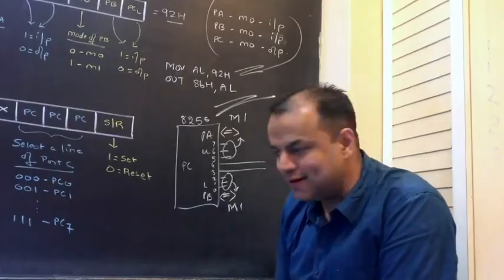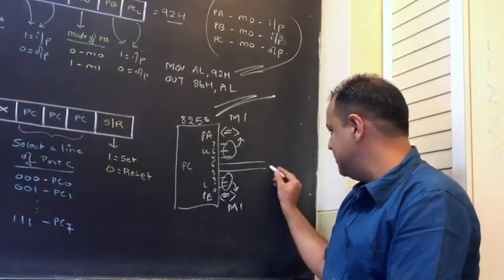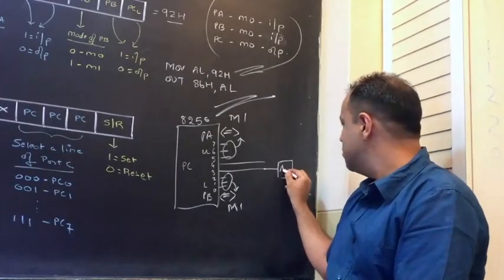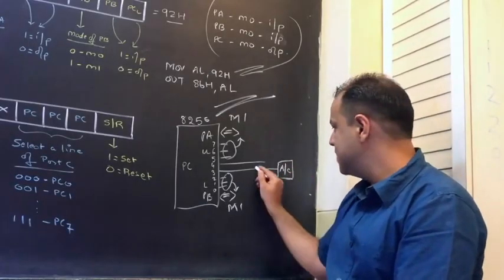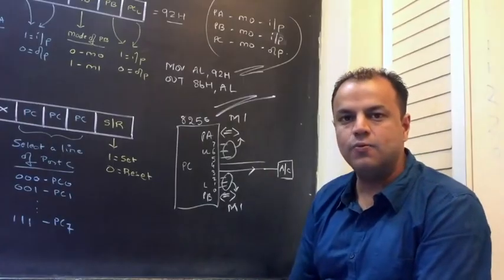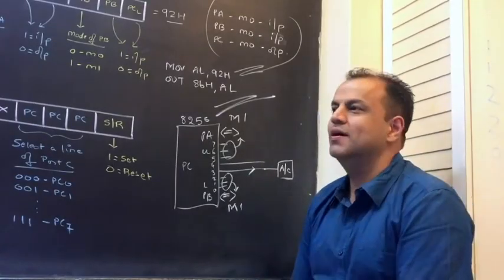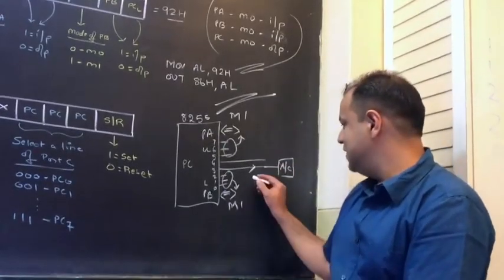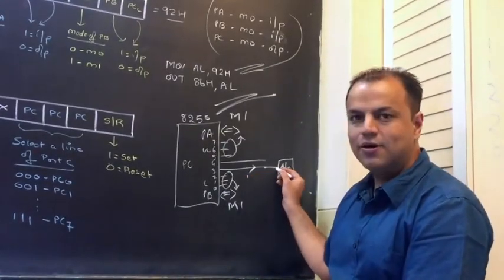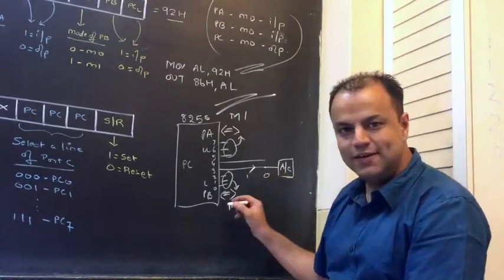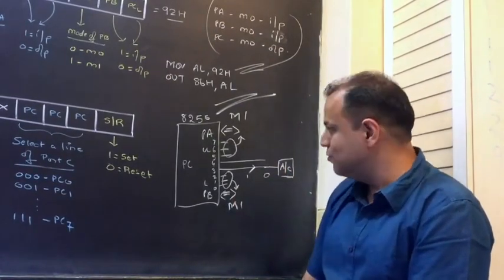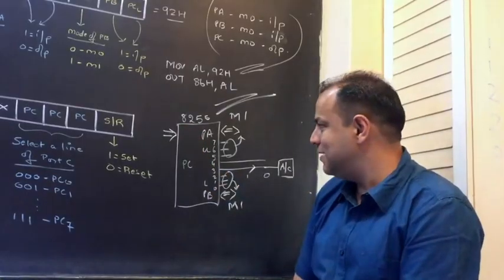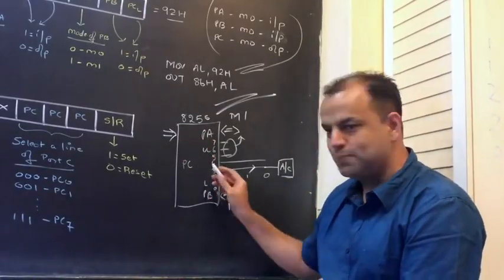How do you use them? By transferring data. Let's say I take line number 3 and connect something like a bulb or a fan or an air conditioner on this line. Now on this line I can send a 1 or a 0. By that I can turn this air conditioner on or off. If I send a 1, I turn it on, as an example. If I send a 0, I turn it off. Now to do that, I will be sending data to 8255 and I will be directing it towards port C.